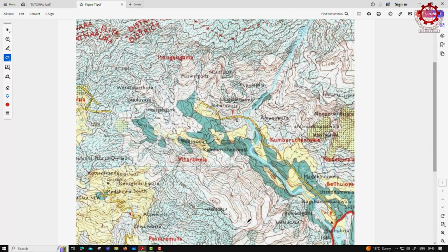So, refer to that section where we discussed contour maps, and then you try to do it. In selecting, now this is a good river, but do not select these hairline small rivers and streams. They are very small, and their catchment area will be very small. So, do not select such rivers for your project. Select something like this main river, where you have opportunity for potential power projects.